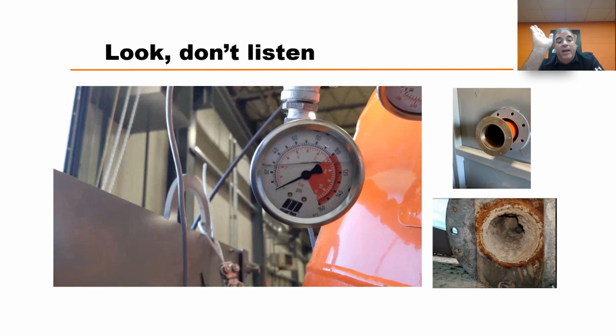If it was completely plugged, it will go from 100 psi or 6 bar or whatever it may be down to only 4 bar, because the air tried to blast out of the cannon, went down a pipe, met an obstacle, and the air came back into the tank. So just listening to it, nobody can tell, or not very many people can tell, especially in a loud environment, that the cannon's working.